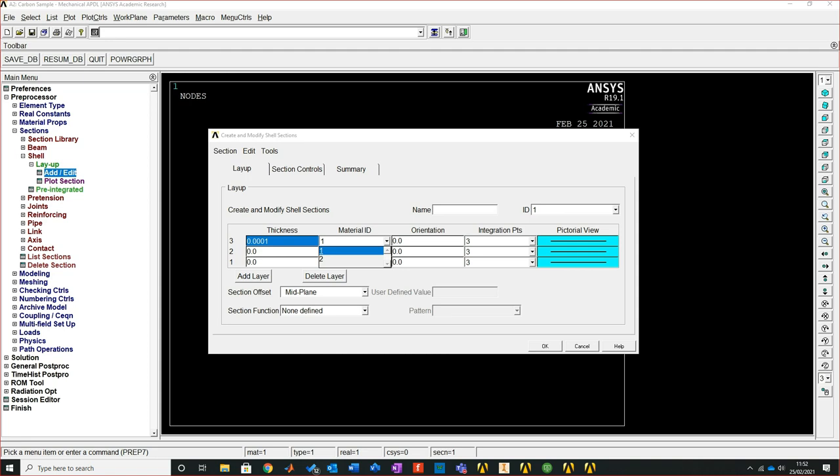And you see there I've got material by ID. I'm setting that to 1. So that links the two relationships together. Now orientations, this is as literally as it sounds. This is presuming that the x coordinate is your beginning orientation, so if you imagine that's your layup and they're all on top of each other and they're all in line, if I set that to 90, you see there, it gives me that little drawing, and it's just to give you an idea of where these layers are sitting when it actually operates.